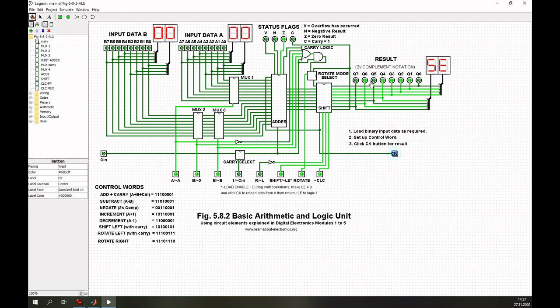Do you see? This 0, 1, 0 pattern appeared again from the right. So rotate left means that the bits which disappear here on the left will be sent to the right again, so that we have a rotation here. So again, take care on this one. The 0 now flows over and comes back from the right. The 1 flows over and comes back from the right, and so on. So that at the end we have again just a rotation here.